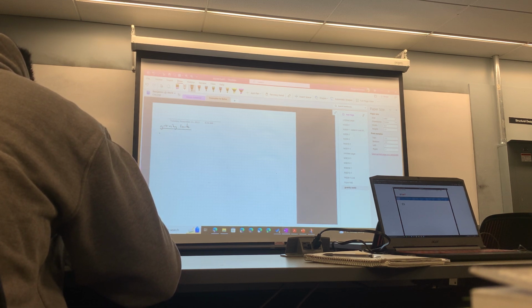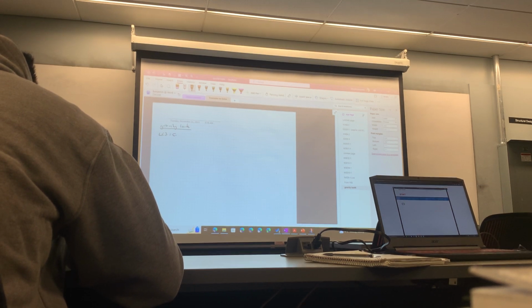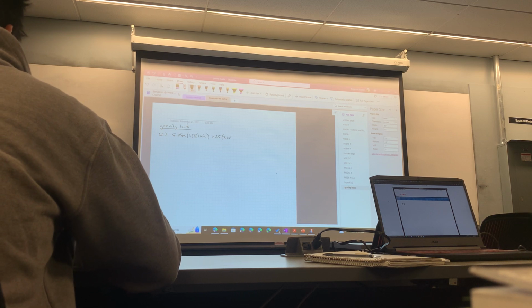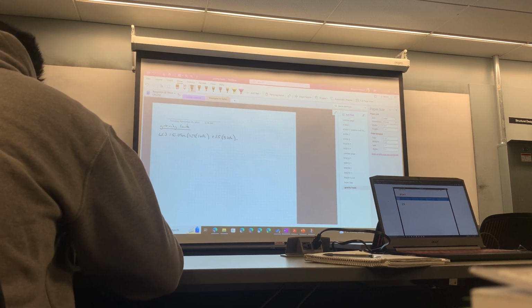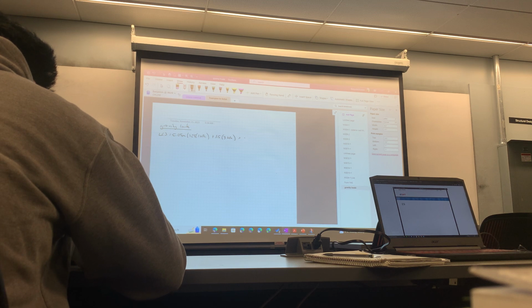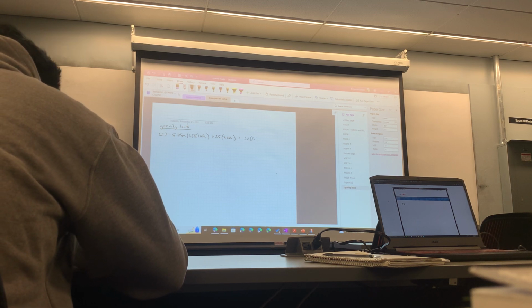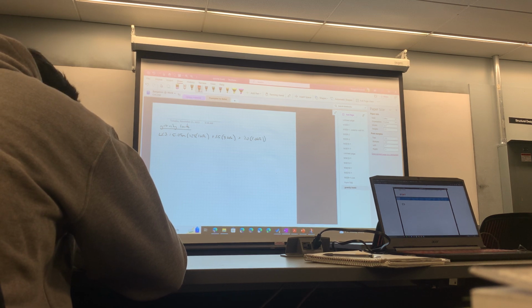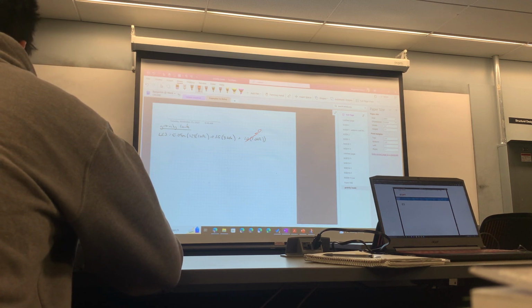To find WF, we're going to use load case 3: 5.05 meters times 1.25 dead load, which is 1 kPa, plus 1.5 times 3 kPa snow, plus 1.0 live load, 1.0 kPa on the roof. That one is 0. We don't have to consider it because it's a roof.